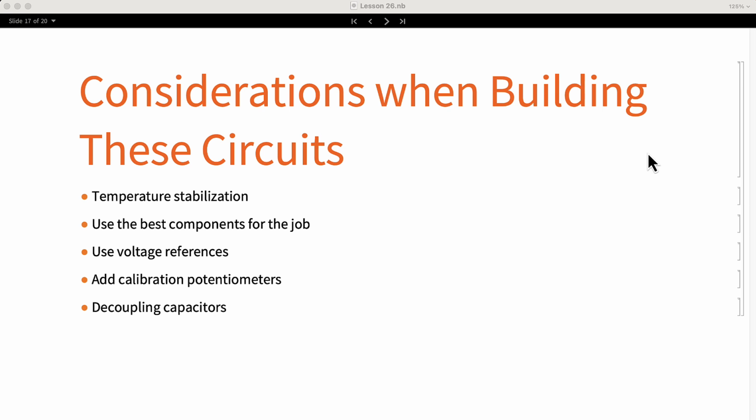Decoupling capacitors are a must for all circuits. They help the power distribution by having a small reserve of energy close to every IC. In my modules, I did not add many of them, and I found that some of the circuits do need it, like the comparator. In general, it is good to add them.